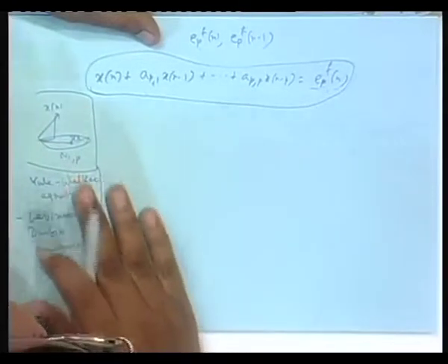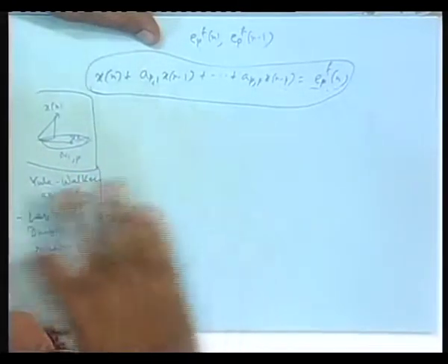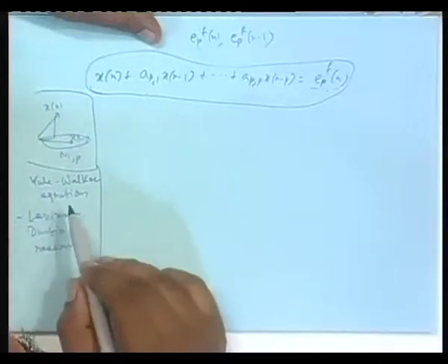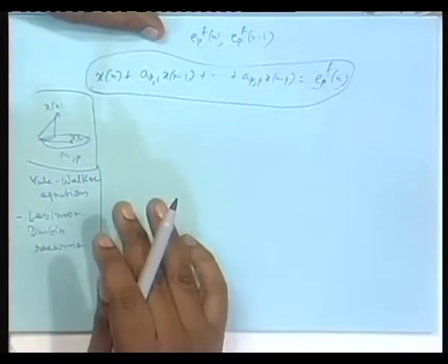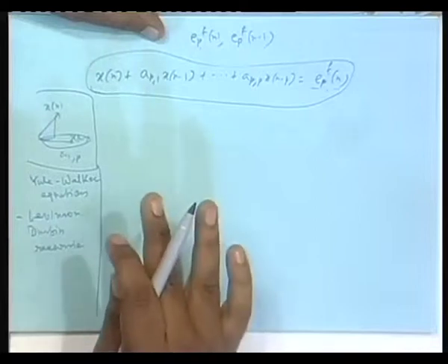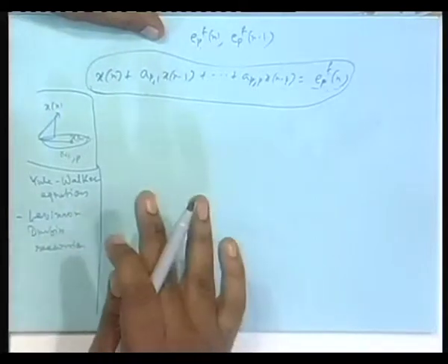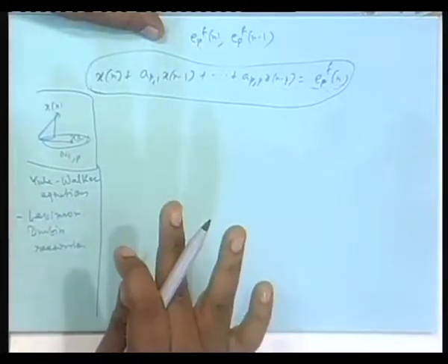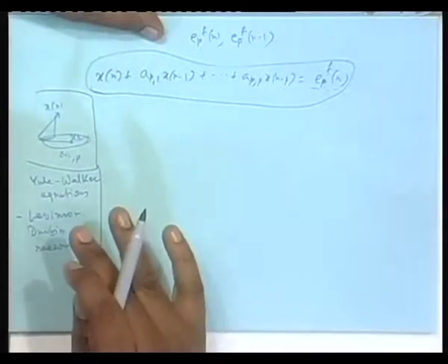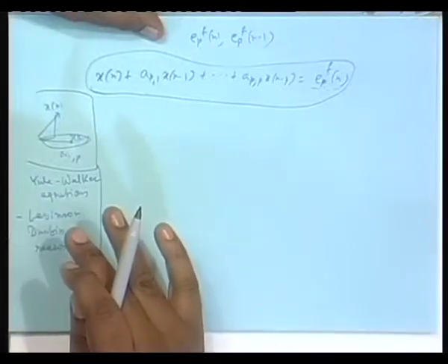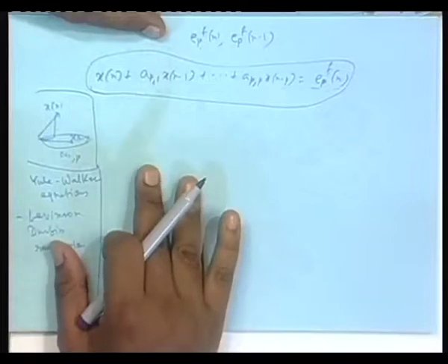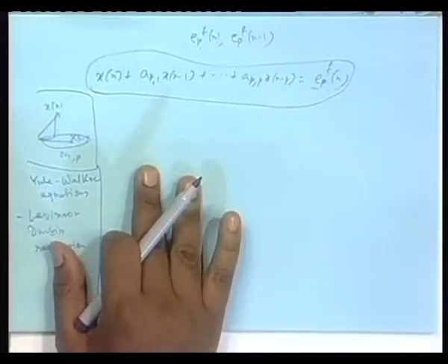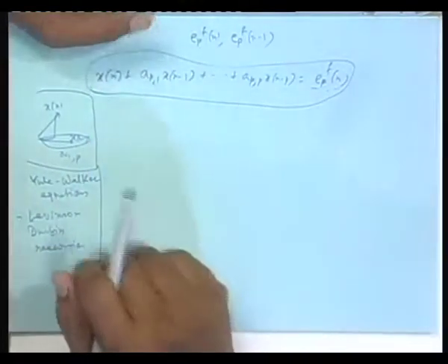We have done this Levinson-Durbin already without knowing that we are solving a set of equations. Remember, I obtained a p plus 1 comma i, all those coefficients, from a p comma i and b p comma j, that is Levinson-Durbin recursion actually. But in textbooks, on spectral estimation especially, they approach this entire thing from just an algebra point of view.